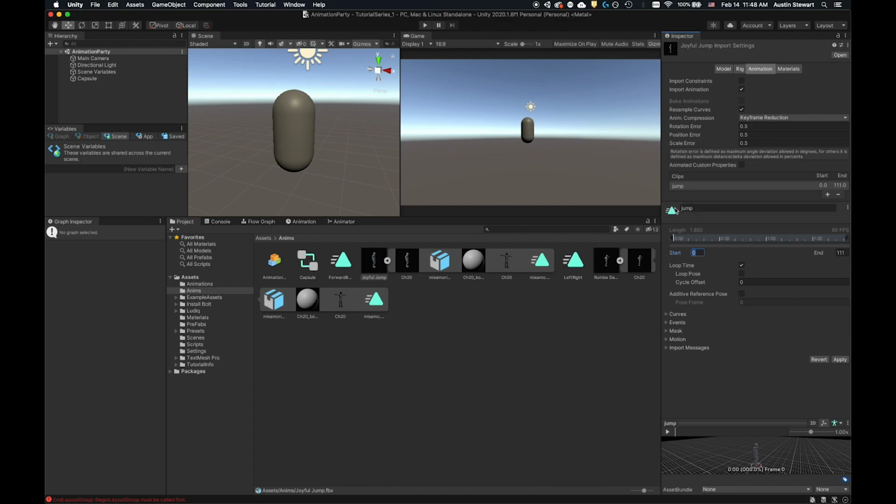It may be that I wasn't out of that setting. So just hitting tab jumps me down to this next thing. Just don't type any numbers or you're going to change the start position of this. So if I click apply now, there we go, now it's set. That's something that's gotten me several times: I think I'm setting it here, but because I still have my cursor in this, it doesn't actually set it even when I hit apply.